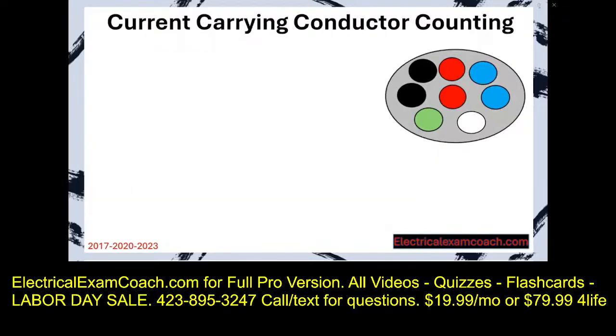Now let's learn about current carrying conductor counting, because we're only going to be counting the current carrying conductors. You may get a question on your exam that gives you the number of conductors. That's easy. You're going to go to the tables and do the math. But you may get a question on your exam that asks you, in a scenario of wires, how many of them are current carrying conductors. The first one's easy: all ungrounded conductors. All of the hots are going to be considered current carrying conductors under normal circumstances.